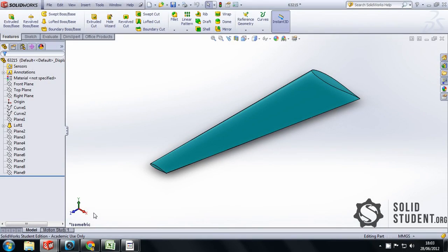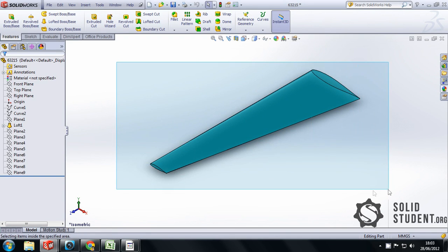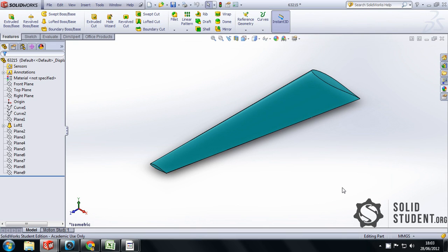This tutorial is on the insert curve function in Solidworks. If you're trying to model a component with curve geometry, reaching for the spline tool will probably be your first instinct. Unfortunately, while you can achieve pretty good results with this method, it's not 100% accurate and will fail at faithfully reproducing complex curves like aerofoil sections, parabolic curves and involutes.